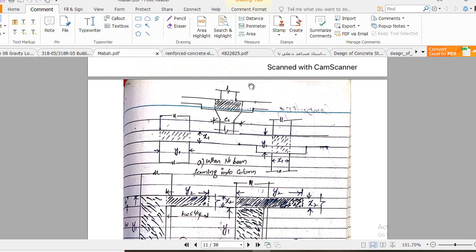Okay, so a transverse section. This is our analysis direction, and this is our transverse direction. So in the transverse direction, if you have a drop panel plus slab plus column capital, in that case this is our effective section, and this will be the depth of the transverse section, or you can say a transverse beam, and this will be the length. So this longer side will be our y and the shorter side will be our x.